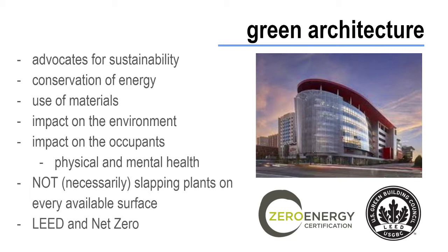And then another very, very popular one is LEED certification. So LEED then takes into, I believe now it's 8 different categories where you then can get kind of graded for your building, and they grade differently based on the type of structure as well. So a school doesn't get judged the same way a house gets judged, but it's still looking at different things about how environmentally friendly is your building, as well as the indoor environmental quality.